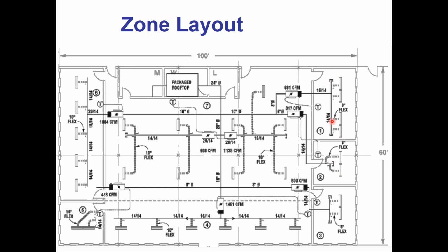That's the main reason why we split those two things up. It's because you never want to put a conference room on the same thermostat as the office space, right? No matter which place you put the thermostat in, it's going to cause complaints in the other space, especially when there's 10 people in the conference room. We got a corner office. He got his own thermostat because he's got exposure to both zones.